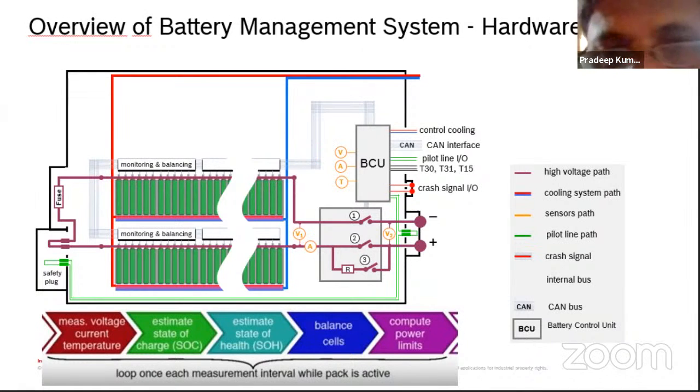Thereby the entire system other than the battery becomes less than 60 volt. Anything more than 60 volt is called high voltage. So it becomes less than 60 volt in the order of maybe a few milliseconds. That is how, in case of a crash, the rest of the systems are taken care of.